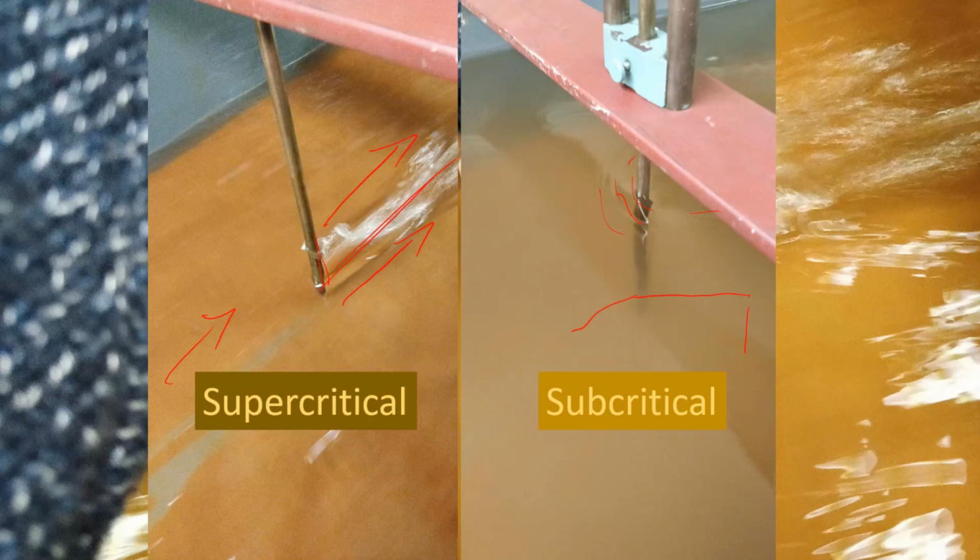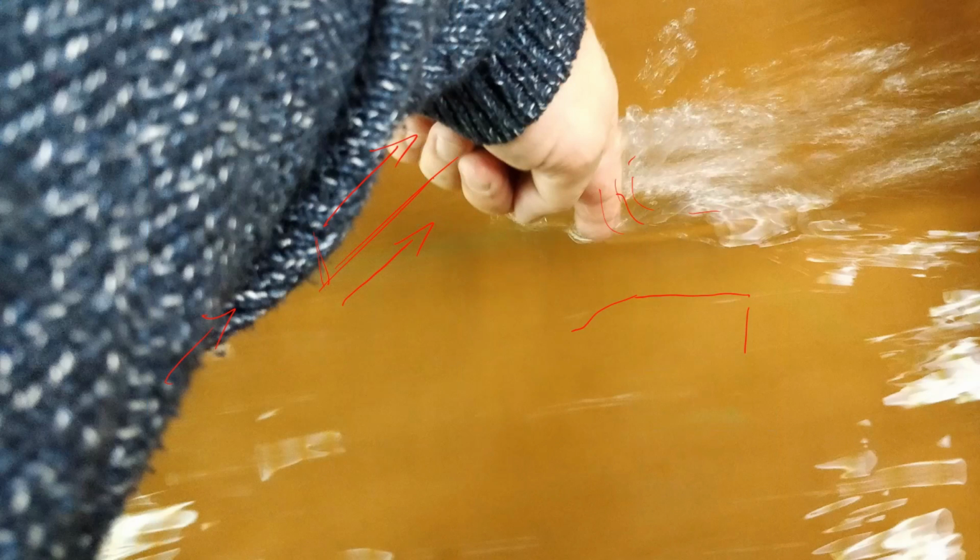So you can do a test for sub or supercritical flow by sticking a stick in the flow like this, or indeed sticking your finger in the flow like I did, and this is in the supercritical flow and everything's going downstream like that.